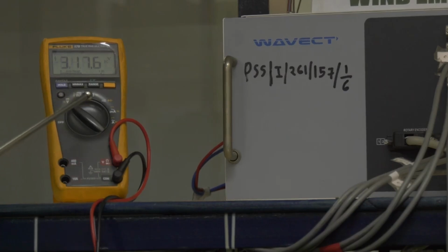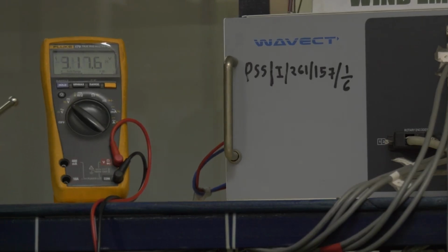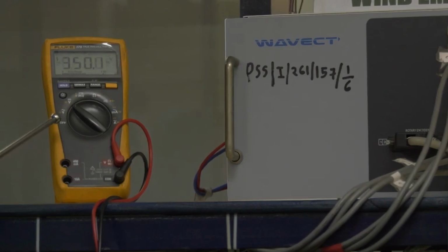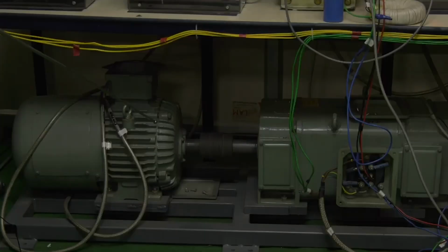Once the DC link is charged, we enable the GSC control to maintain the desired DC link voltage, which is set, say, 30 volt greater than the DC link voltage, that is 350 volts. The rotor of the DFIG is rotated at 900 RPM, which is 10% of the slip, with the help of the DC motor.